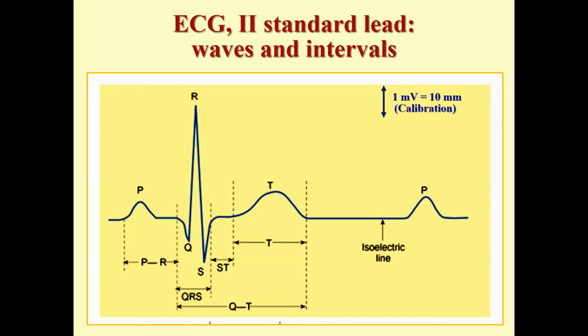It makes a signal of 1 millivolt always go upward, make an amplitude of 10 millimeters. And in the beginning of each record there should be this calibration signal. It should look like the following. This is the calibration signal. When a signal of 1 millivolt comes, the record goes upward and shows amplitude normally exactly 10 millimeters. Otherwise it can be adjusted so that it makes perfectly 10 millimeters. So in this case it's a standard record, and it can be compared in voltage in millivolts of amplitude.